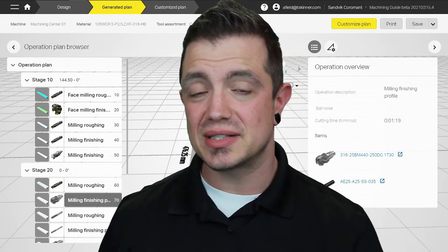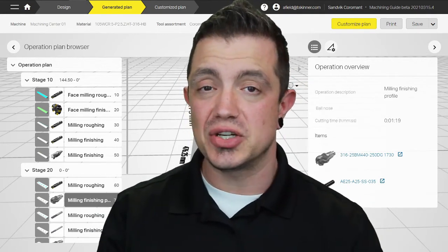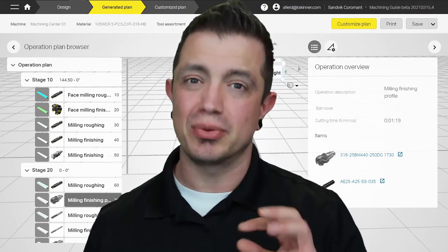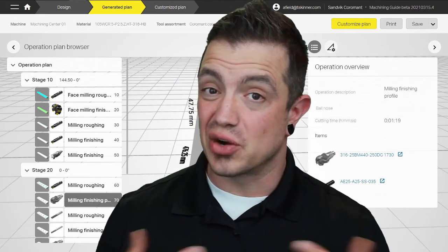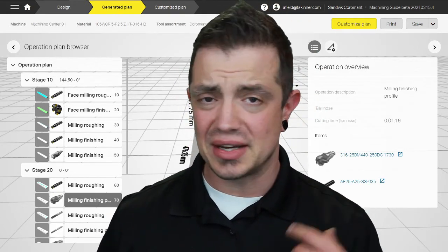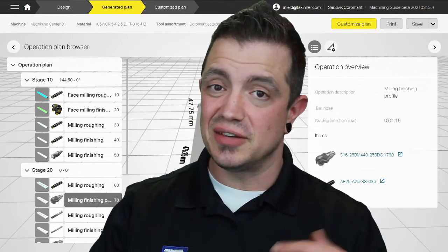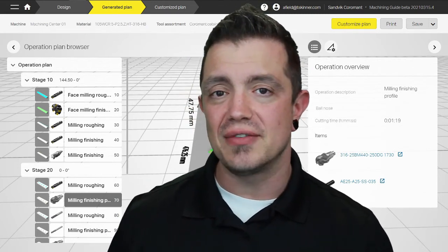However, it would be very simple to hold this part and then take the tooling with the selected orientations. It won't be 5-axis optimized, but it'll get you there. It's more like a 3+2 at this stage of the software. If you're looking for a general machining time though, it's hard to beat the speed this generates at. Getting a solid file from your customer to quote, dropping it in here is going to give you the longer processing time, especially if you are fluent in your 5-axis.